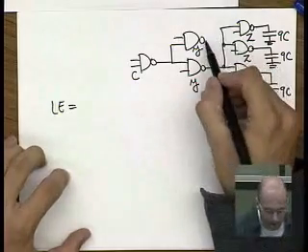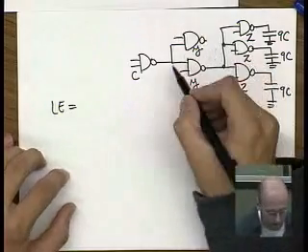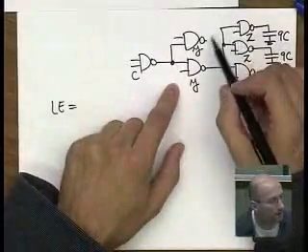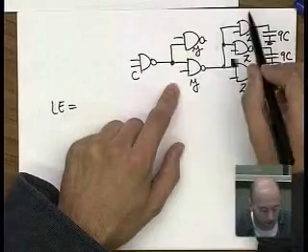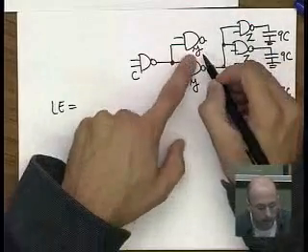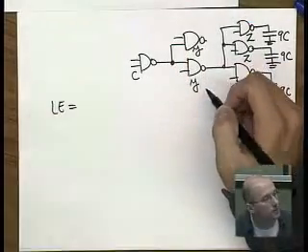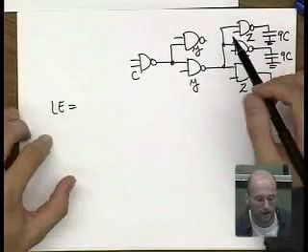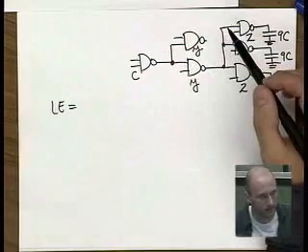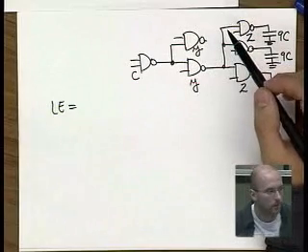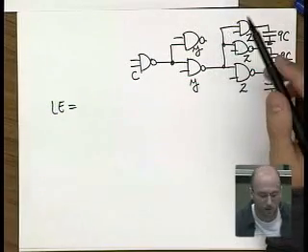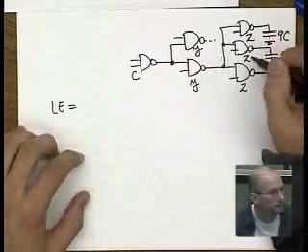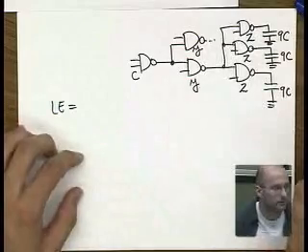That's a very good question, actually. If you assume, as I just mentioned a moment ago, that you don't know what is really coming off this path, and then you may have different delay constraint, then you have to do this y1 and y2, just to make sure you're doing really optimal case. If you just fix the sizes of y's and say, well, I don't know, but let me do the first order analysis, that is still okay, but it'll give you suboptimal solution. So in this case, it assumes that it has the same type of network following this output. That's a very good point.